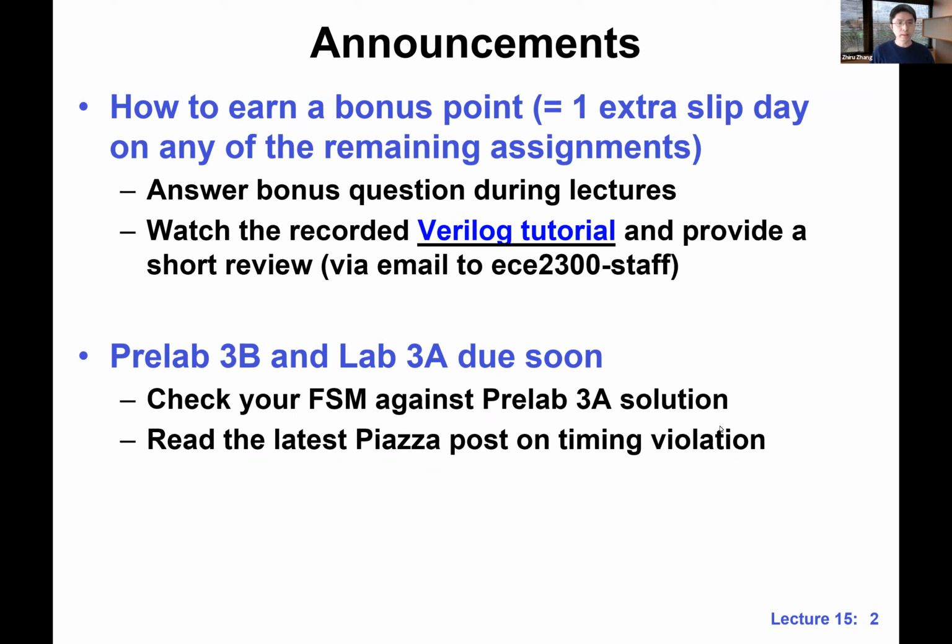And also read his latest post, because we noticed that some of you got your simulation working and passing all the test cases, but it's actually failing to work on the actual FPGA device. That's where you may have a timing violation. You may either have an inferred latch, or you may have a very long critical path delay. That's where you need to look into your design and try to fix the timing issue. Any more questions?